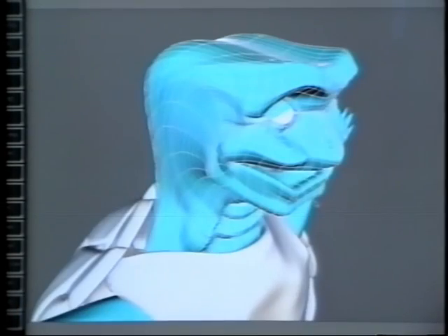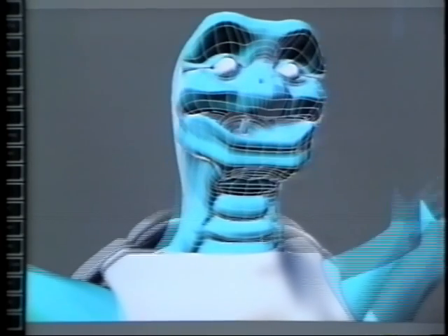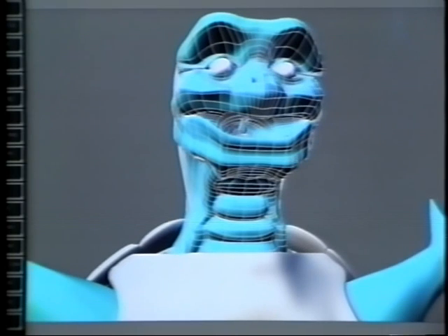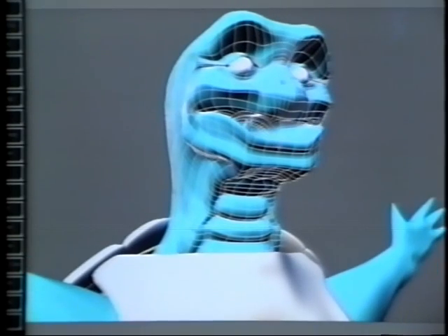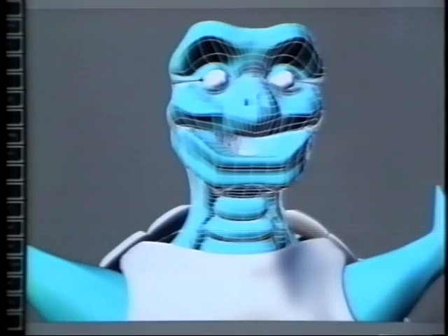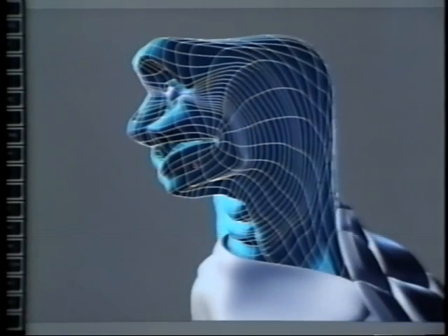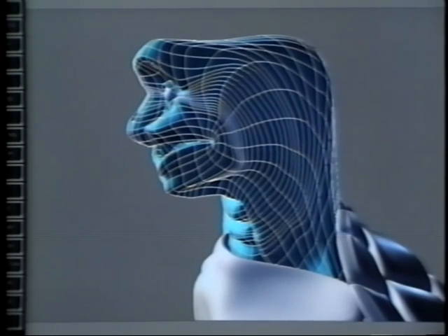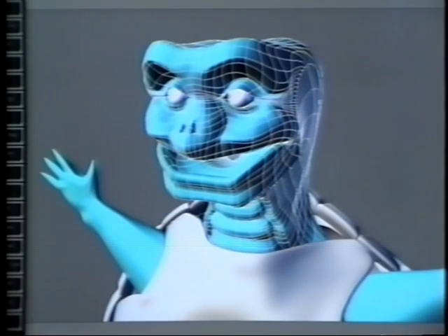I started the last head with a pole at the top, but other parameterizations are possible. Mouth-centered models are just as good for many designs, like this character. Here, one pole is at the center of the mouth, so each curve radiates out of the mouth, then bends down to the open end at the neck. This arrangement gives a lot of easy-to-manipulate points around the mouth, although it would not easily support high levels of detail around the eyes and forehead. So it's perfect for many cartoonish characters, and also for most creatures and animals.